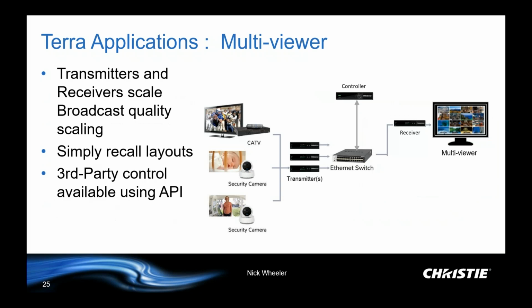The multi-viewer is something that's incredibly useful as well. Here, a single receiver will subscribe to multiple transmitters at the same time and display thumbnails, as it were, of those sources on the screen. Again, the receiver can be any resolution you like. We'll be going more into the multi-viewer and how you can use it in tomorrow's presentation. From memory, I think 34 or 36 is the maximum number of thumbnails that you can display on the screen. So they can be really, really small, and you wouldn't see much. But yes, I think it's 34 or 36 transmitters that can be subscribed to by the receiver.